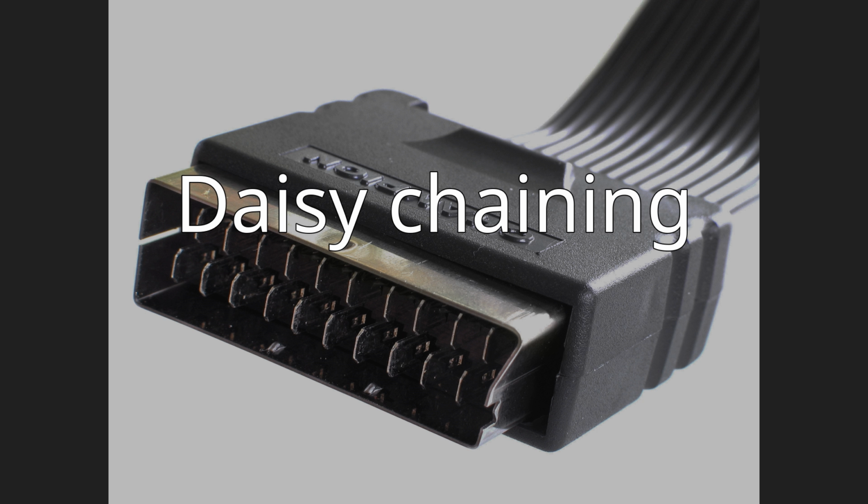A VCR will often have two Scart sockets to connect it to the TV (up, primary or 1) and for video input from a set-top box or other device (down, secondary or 2). When idle or powered off, the VCR will usually forward the signals from the TV to the set-top decoder and send the processed result back to the TV.